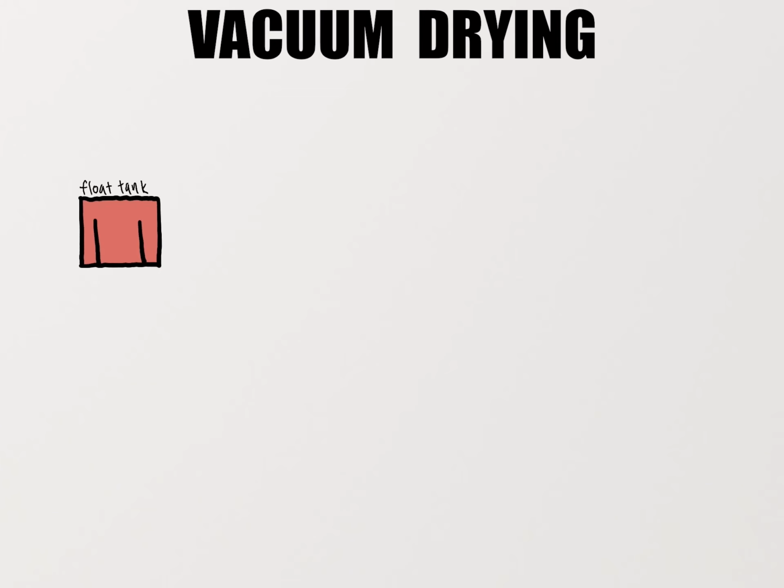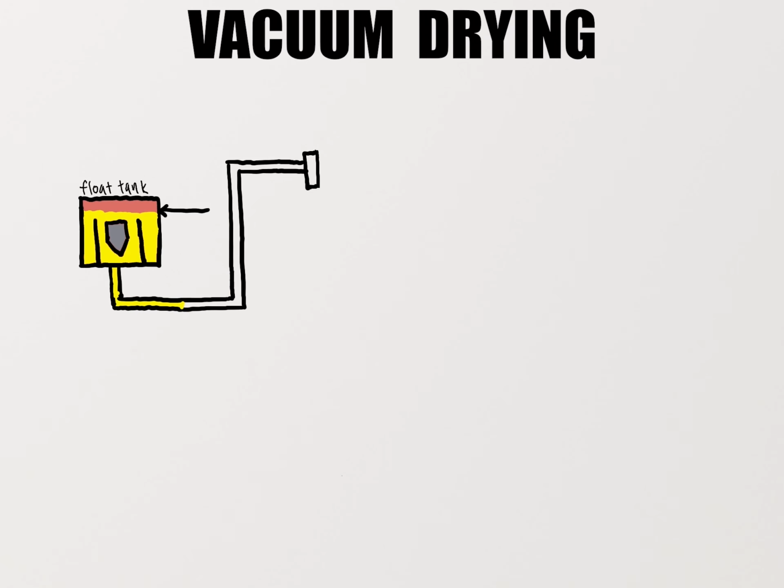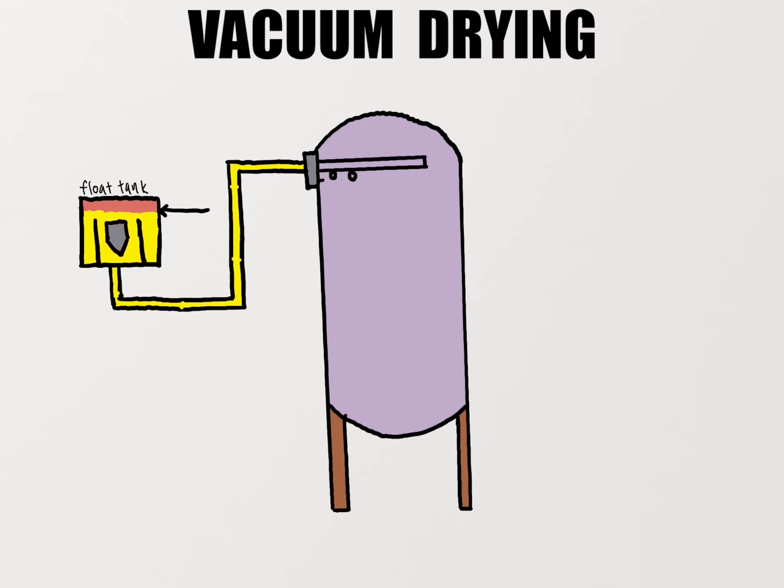The oil to be processed from the purifier will be injected into the float tank. In this float tank, there is a taper spindle that serves as an automatic valve to keep the constant vacuum in the vacuum chamber continuously. In the vacuum chamber, there are 6 spray nozzles that inject oil to the deflector surface.